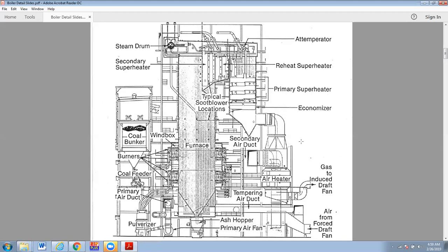into the boiler. The pressurization in the furnace is controlled by the balance between the capacity of the FD fan that's blowing in and the ID fan that's sucking out. The ID fan is basically pretty close to the stack, and it's blowing up the stack, but on the suction side it's pulling stuff out of the boiler, whereas the FD fan is pushing into the boiler.